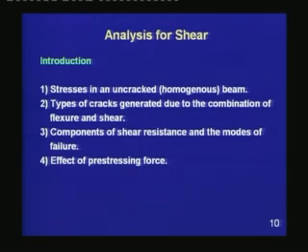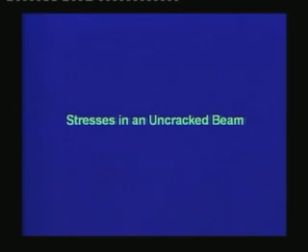Second, the types of cracks generated due to the combination of flexure and shear will be discussed. Next, we shall move on to components of shear resistance and the modes of failure due to shear. And finally, we shall see the effect of prestressing force in the shear resistance of the concrete member. First, the stresses in an uncracked beam.